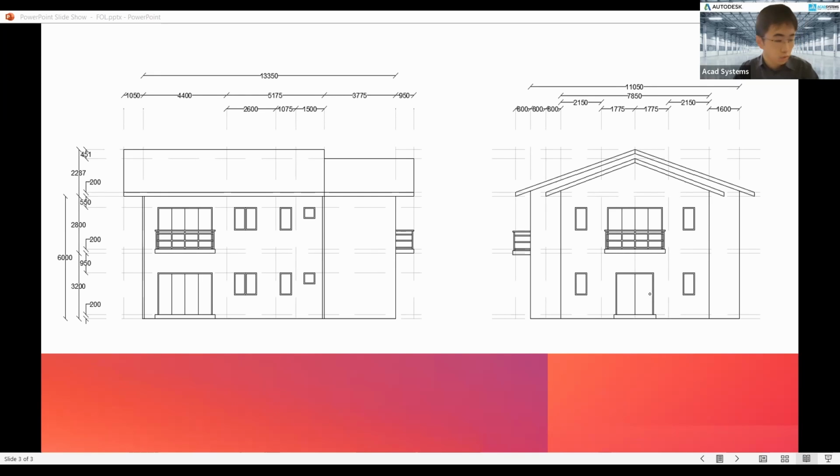In this isometric drafting, we have three isoplanes, which are the left, top, and right. You can click on this drop down here to switch in between these isoplanes, or you can press F5 on your keyboard to switch in between these three planes. You can type L in your command bar to draw a line, or you can press on this button.